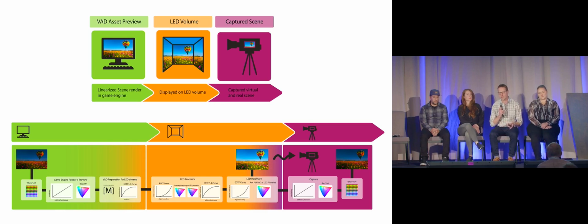And the concern is when it's not a linear physics problem that is falling apart, the matrix is going to be insufficient. So it's a space really rich for some innovation and accommodation of improvements and monitoring of the actual places where linearity can fall apart. You may not have an engine that is applying the exact inverse EOTF of the LED panels. So you may have an accumulated nonlinearity. You can't fix that with the 3x3 matrix.